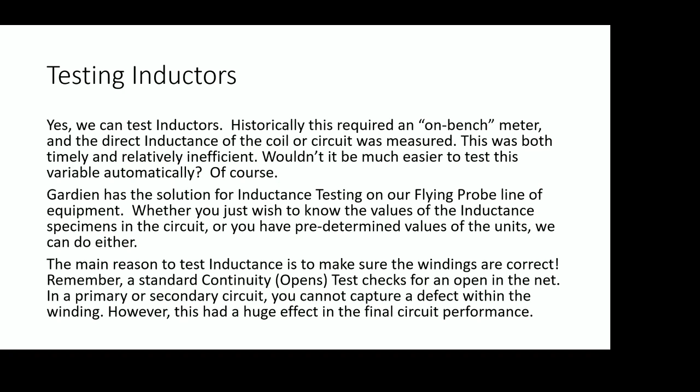I would recommend, based on technology today, especially where we're going with microchips and a lot of regenerating the activity here in the US, we want to make sure that our quality is as high as it can be. And I really think we need to look at the electrical signature analysis of inductive circuits, just like we do with resistive components and capacitive, because these have an effect on today's circuits. So I would rather, in my opinion, see an electrical validation of a buried inductance in a PCB.